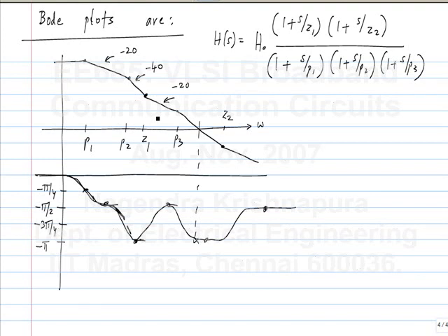Okay. Now, if the number of poles is more than the number of zeros by 2, you get a phase lag of pi, right? So, it has to be only 1. So, you can have many poles and zeros, but the number of poles can be greater than the number of zeros by 1. That's all. Okay. Is this clear?